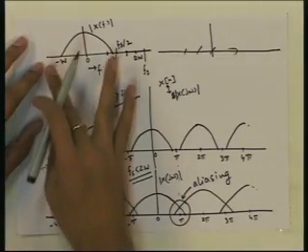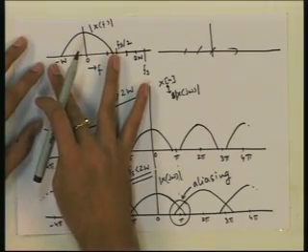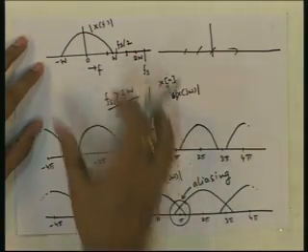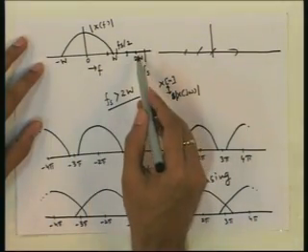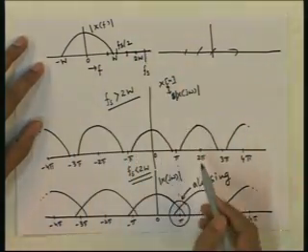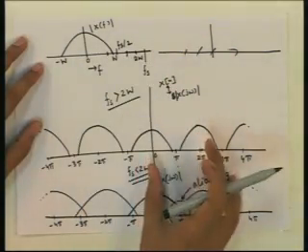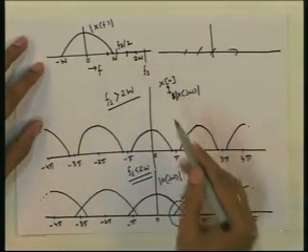Then we have seen why it should be true in the frequency domain. When you discretize the signal and we take the DTFT, the DTFT of the signal is obtained from the original signal by shifting the spectrum of the original signal at multiples of 2 pi after scaling so that Fs is mapped to 2 pi and all the other frequencies are mapped to intermediate frequencies linearly.